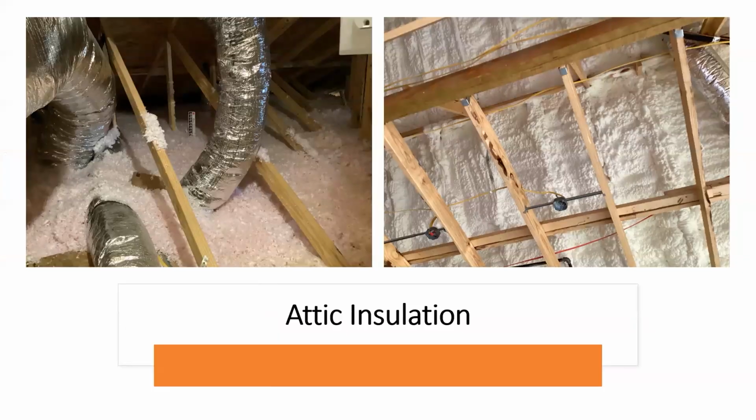And then we've got attic insulation. It's pretty easy. Usually, if you make sure that the markers are done correctly, it's easy to see. If it's all level, it's not peaking at all the markers, and it's meeting that R value, it's grade 1. On the right, we've got foam. It's an encapsulated attic. You see the peaks of every single rafter. They covered each rafter, which in my opinion is a great way to do it. You're blocking thermal bridging at the peaks of all those rafters. So you're making sure that's all covered. If you see those rafters being covered like that, you can assume that if that's a 2x6 rafter, it's actually 5.5 inches deep.